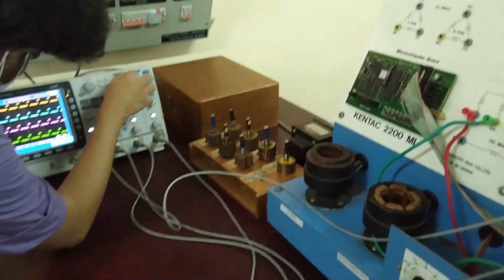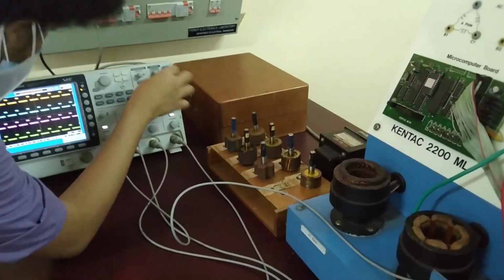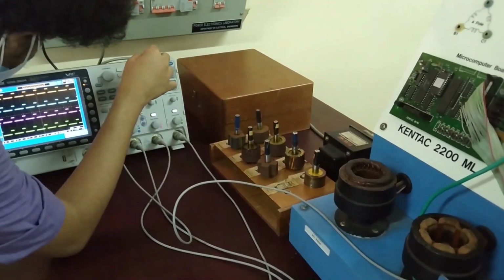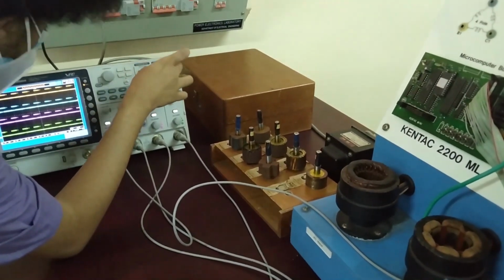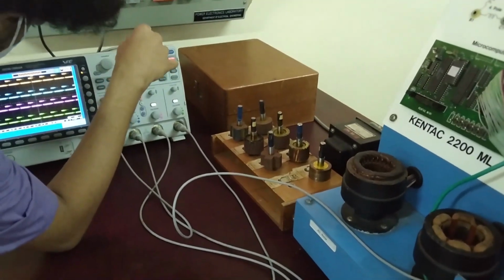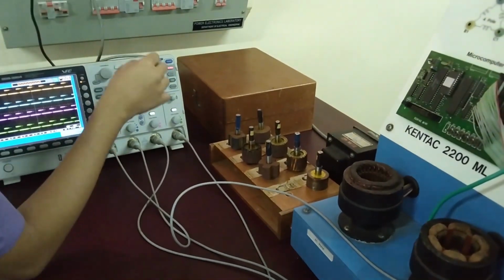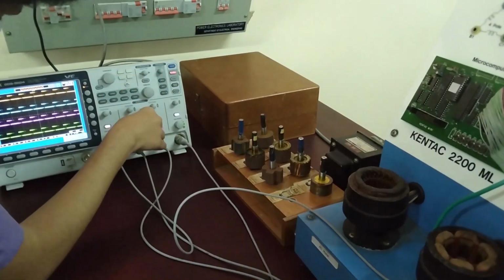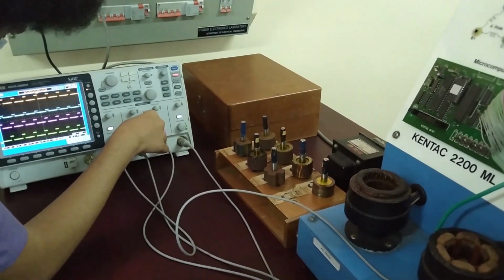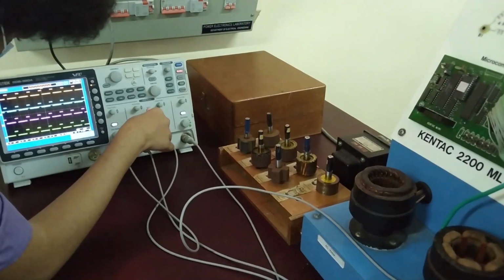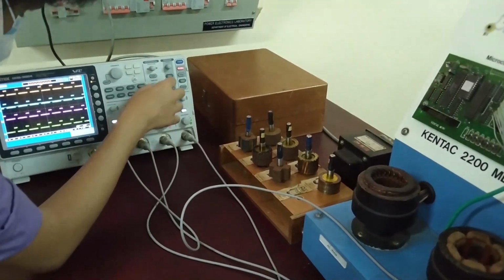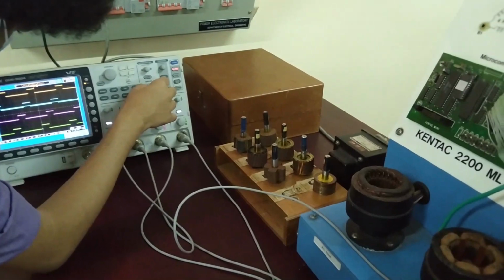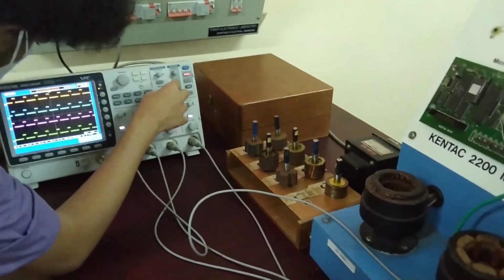Observations from the oscilloscope. Here, we are using an oscilloscope to observe the switching signals. All the 4 channels of the oscilloscope are used in this practical since this involves a 4-phase stepper motor. Let's have a quick look at the oscilloscope plots for each mode of operation. You can calculate the time period between pulses using these plots, and it will be needed for your calculations.